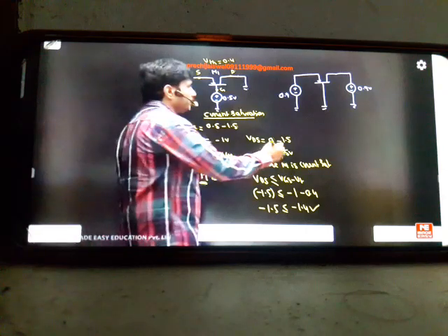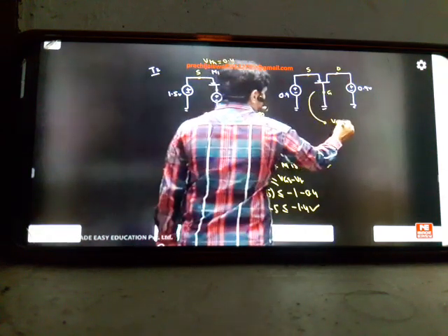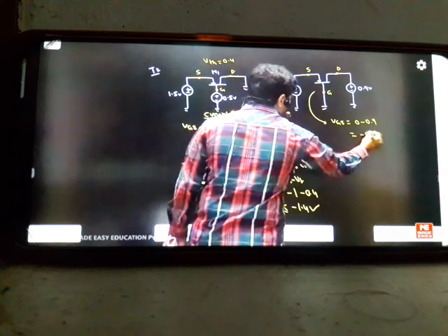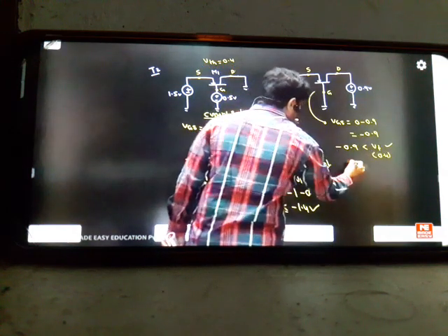And coming to the second point, have you observed the trick? This is source, this is gate, this is drain. First you finish here: VGS value 0 minus 0.9 will be minus 0.9. So minus 0.9 is less than your threshold voltage 0.4. So I think M is on, first confirmed.